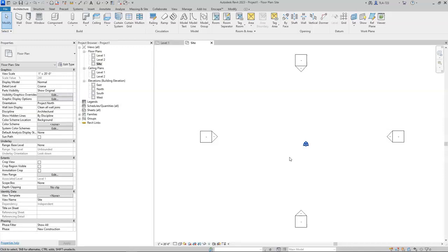When we're working on a building, we may not want to clutter it up with a bunch of topography. Now, I'm not saying you have to do it that way for your final project. If you want to just create the topo right in your final project, that is fine. It's going to work just fine. But for this operation, we're going to do the link operation just for practice, because this is commonly used, linking two projects together. Very common to do in a Revit environment workflow.